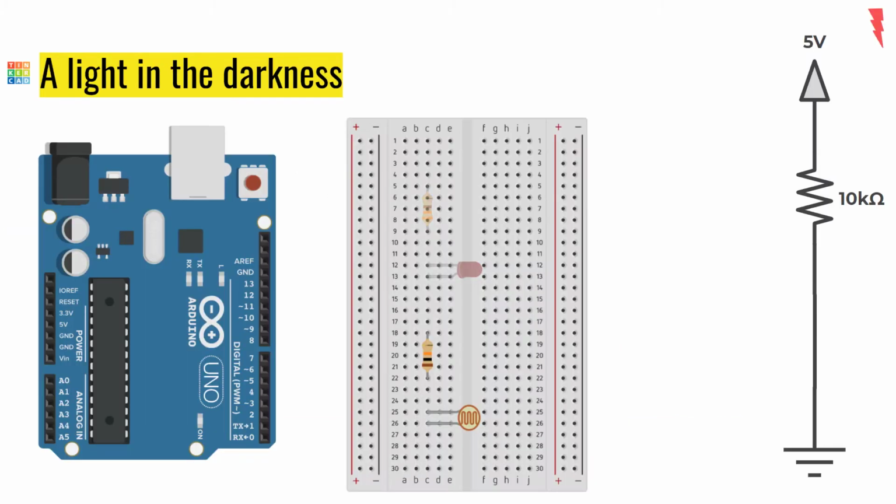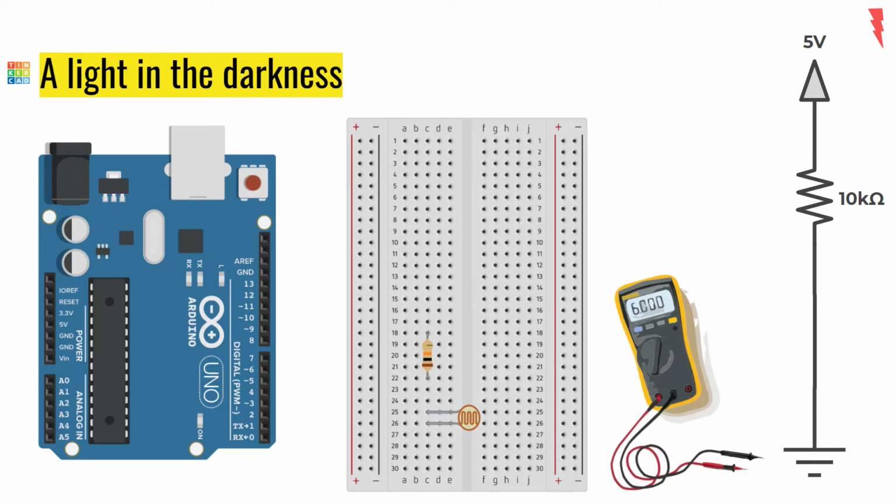Remove the previous LED circuit, and let's get started with the new piece of hardware. We're going to be hooking up this sensor in a way that allows us to notice a change in the amount of light the sensor is exposed to. To do so, the only thing we want in the circuit that can change is the photocell. Everything else needs to be constant. When we set up this circuit, we'll be using the constant 5-volt supply from the Arduino.